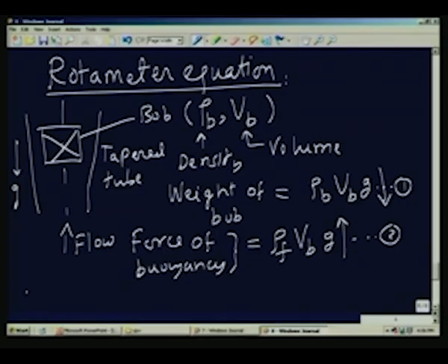Okay. There is a third force which we called the drag force, and most certainly it is not due to viscous effects. It is only due to the shape, the way the flow negotiates the body, and therefore it is mostly due to the form of the object. Therefore, it is called the form drag.